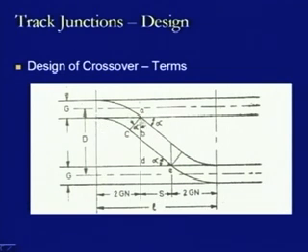So, this curved lead is there between these points, and this curved lead, as we have seen in the design of turnouts, is equivalent to 2 times G into N. So, this horizontal distance is 2 times G into N. Similarly, this horizontal distance related to this curved lead will be 2 times G into N. This is an approximate value for finding the curved lead here, and then in between we have S. So, the total length L, that is the length of this crossover, will be nothing but S plus 2GN plus 2GN.